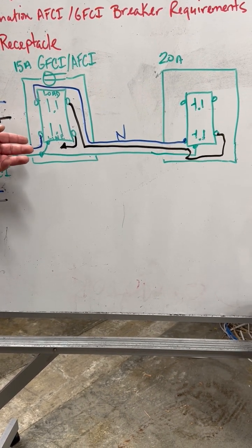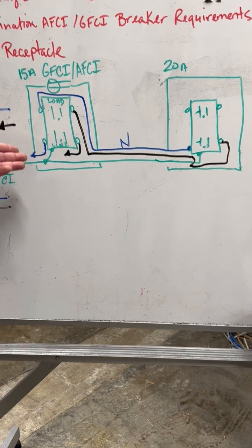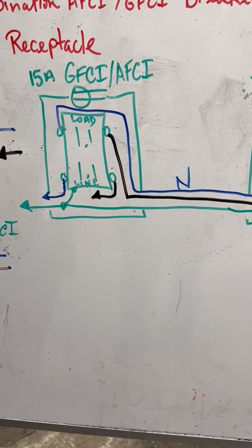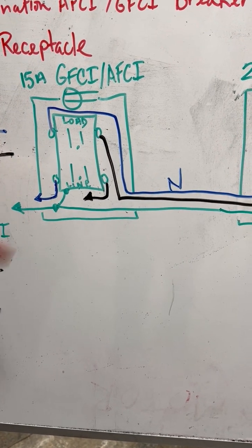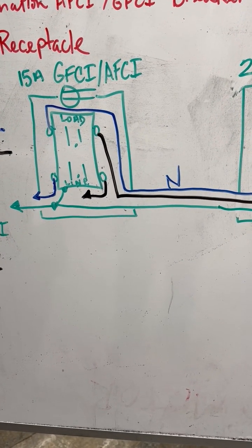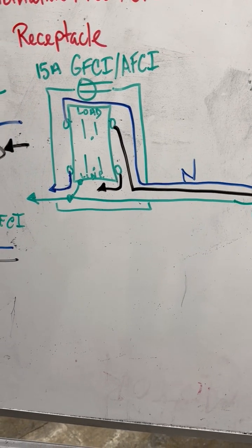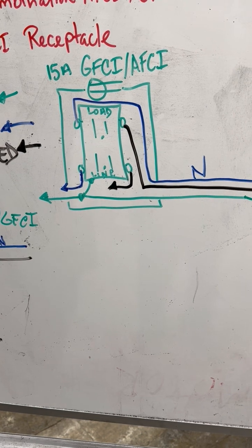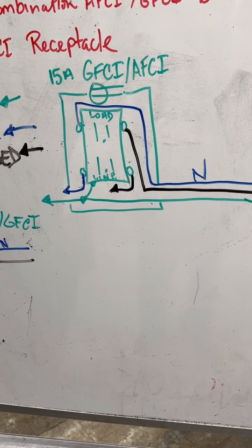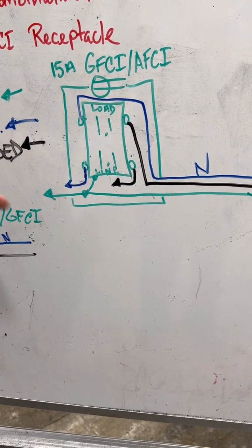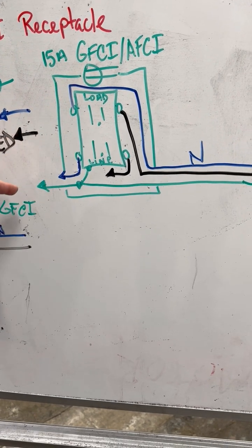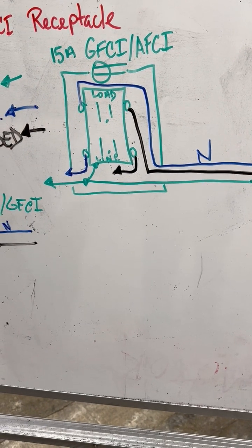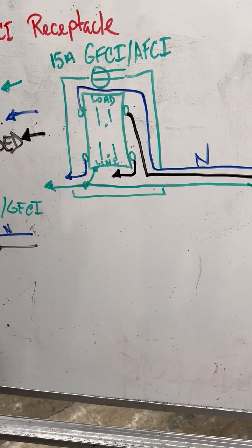They also get the explanation of the wiring schematic. So I try to make it as simple as possible, showing the conductor colors, illustrating them here on the side, telling them what the little arrow tip means about the home run, to make the drawing and the illustration of the lines more seamless, so it's not so confusing and too much to understand. So we have our home run grounded neutral, our home run grounding circuit coming in here, and our ungrounded conductor. Another thing I point out to them is wire management in this illustration.